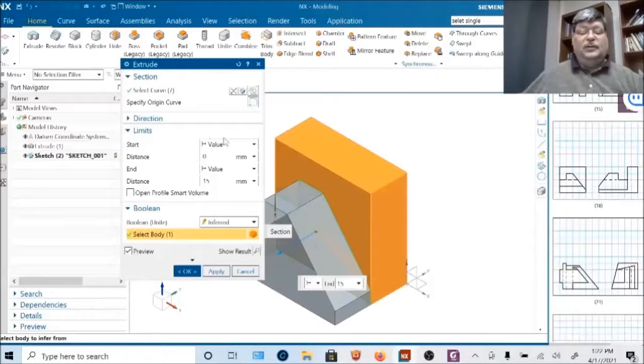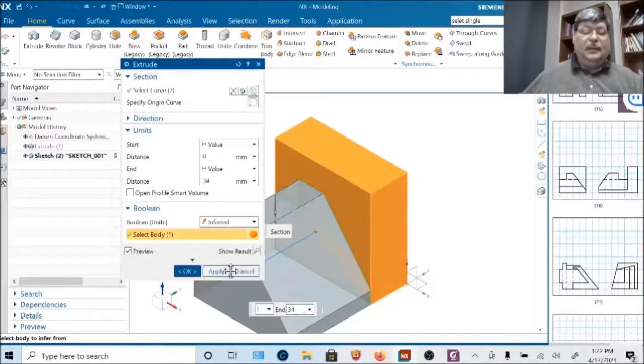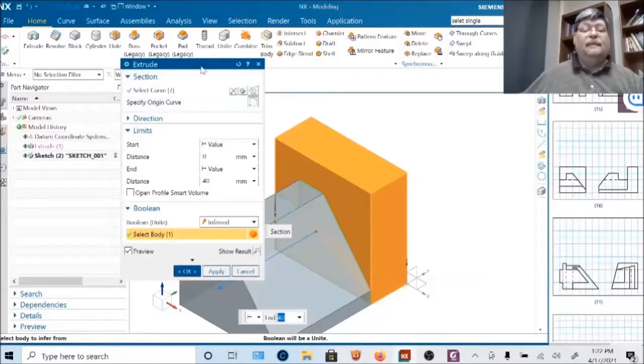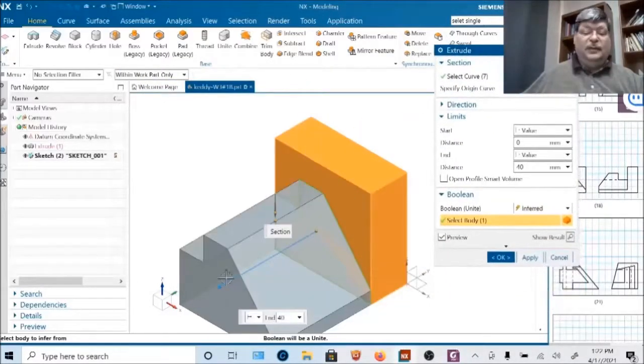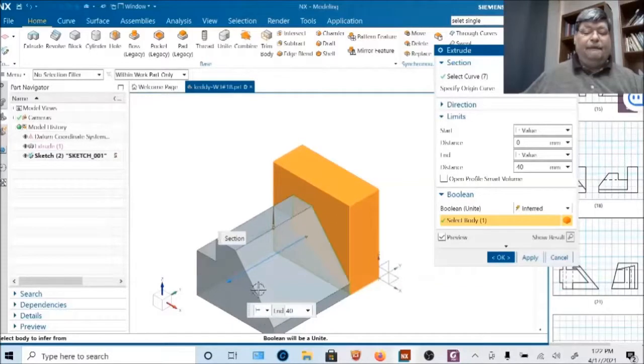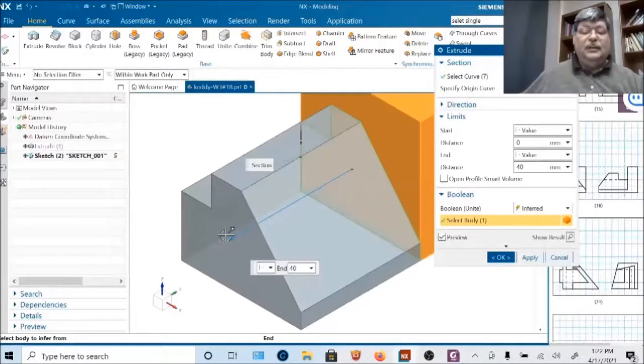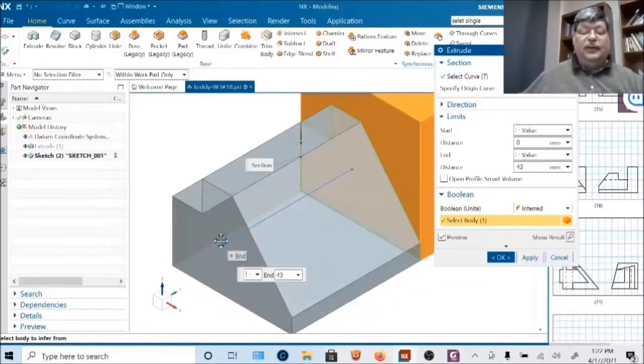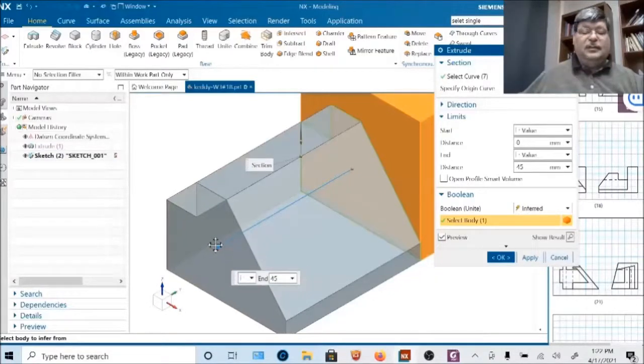Finish. And going to extrude this out. What is that? 45. Yeah, you can pull on the arrowhead or on the ball. This is the start. This is the end. You can move these if they get in your way. And so this one should be 45. If it's a whole number like 45.23 or something, you have to type in. But usually you can drag it.